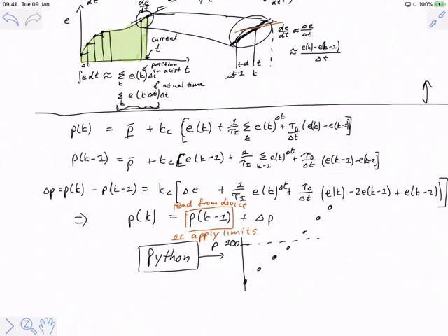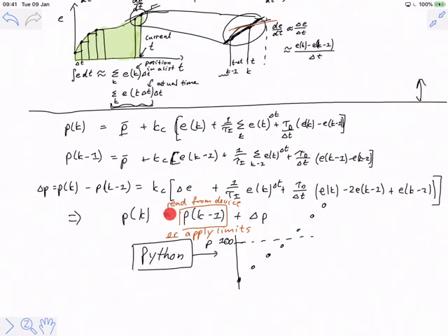In the velocity form, it is completely obvious where the previous output value should go. It should go here inside this red box. But the key thing is I should be reading it from the device or using my previous value subjected to limits instead of just whatever the formula spits out.